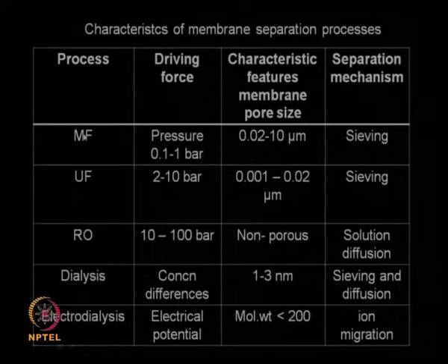If you look at microfiltration, generally it is operating at either vacuum or near atmospheric pressure, so it can remove large particles, 10 micron particles. The principle is based on sieving, that means it has a lot of pores, and depending upon the pore size, if the particles are larger than the pore size, they get captured and smaller particles and salts travel through.